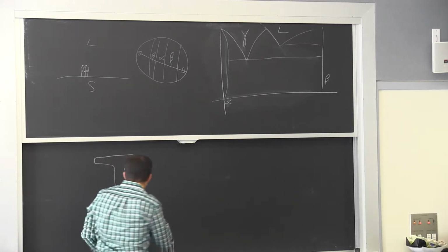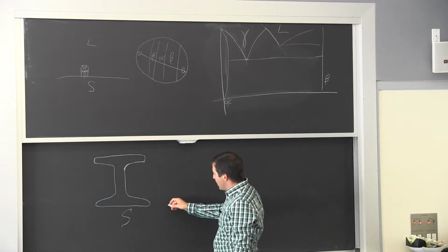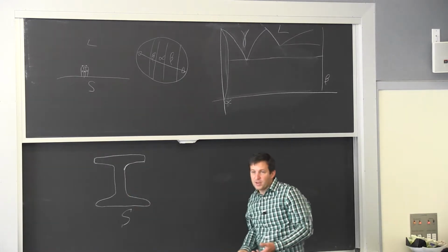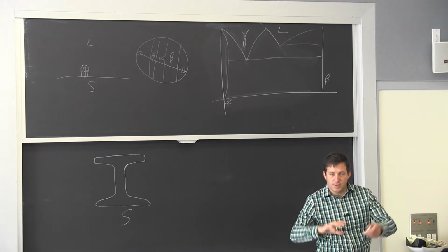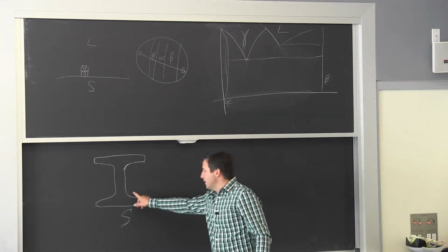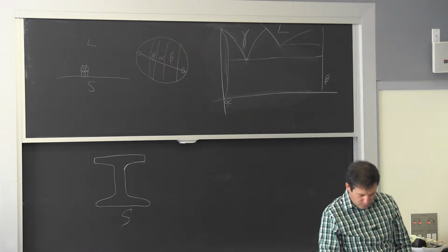So that's an S type of I-beam, and then we started making wide flange that have this a little sharper just by improving all the rolling technologies, the lubricants and all that, but you still have a radius here that is much bigger than what you have in that laser welded beam.